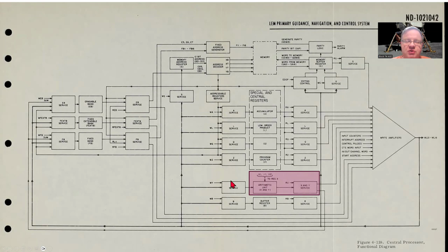In the second episode, we talked about the adder, which forms the arithmetic unit of the Apollo guidance computer, and how it adds the contents of the X and the Y register. And today we'll talk about the output, how data gets out of what we now call the U register, or the summer, the outputs of the arithmetic unit.